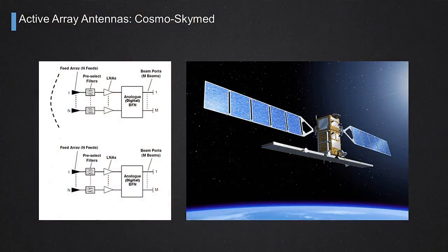We said that some direct radiating antennas, in fact also some reflector antennas, are active antennas. We introduced the concept of active antennas when speaking of the reciprocity principle. We said that the reciprocity of antennas applies when the antennas are made of reciprocal components, not including, for instance, active components such as low noise amplifiers or power amplifiers. Shown in this slide, on the left side, are two examples of receiving active antennas.